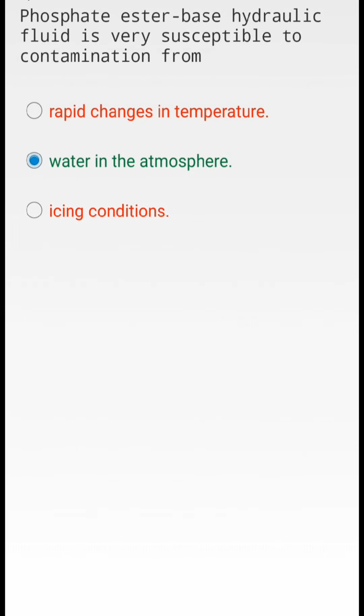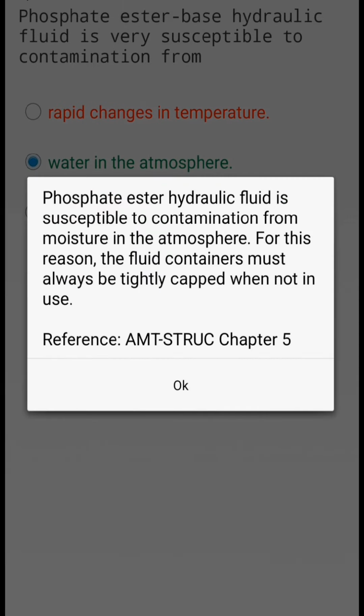Phosphate ester base hydraulic fluid is very susceptible to contamination from water in the atmosphere. Phosphate ester hydraulic fluid is susceptible to contamination from moisture in the atmosphere. For this reason, the fluid containers must always be tightly capped when not in use.